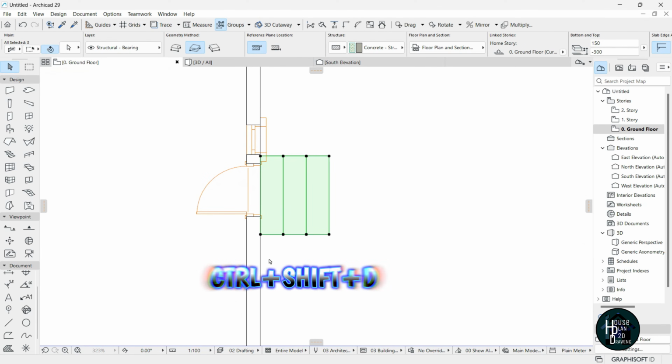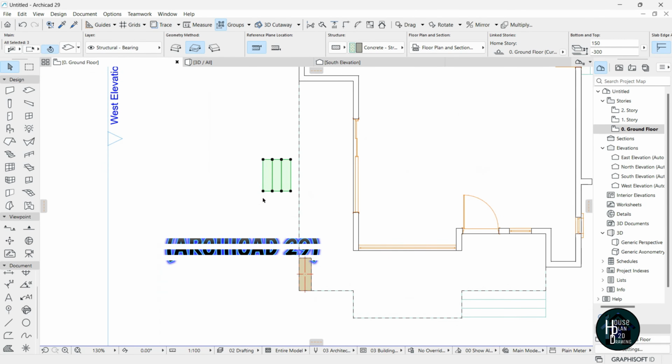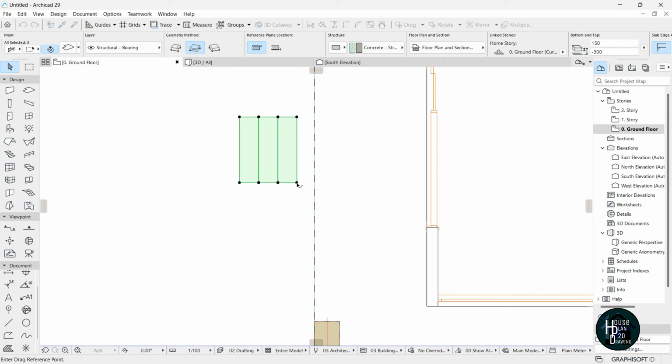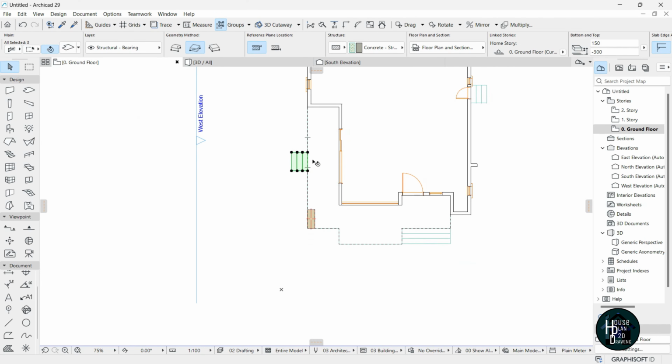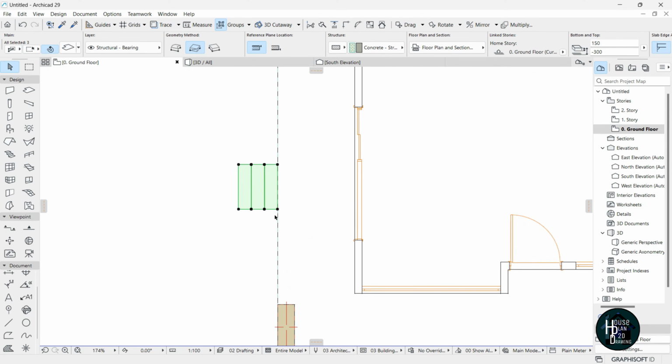and I'm going to highlight all of this, press Ctrl Shift D on the keyboard, click this, and let's try and move this somewhere around here. Press Ctrl arrow. Okay, press Ctrl arrow again. Okay, and that should adjust itself. Go to press Ctrl D and just put it here. Okay, let's see. You have the door here, so let's try and just place it somewhere around the middle.